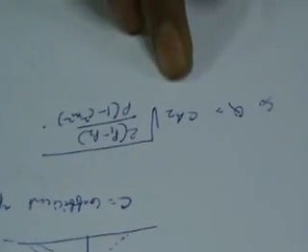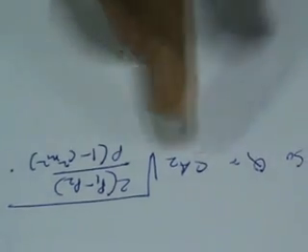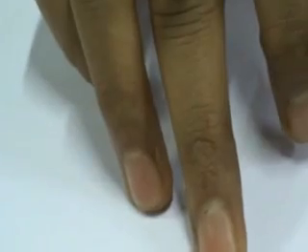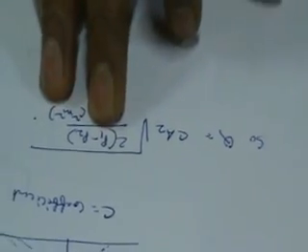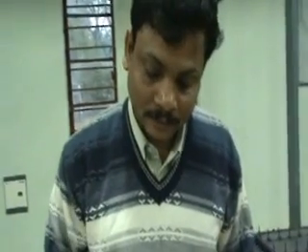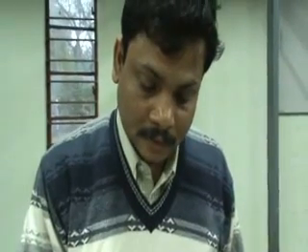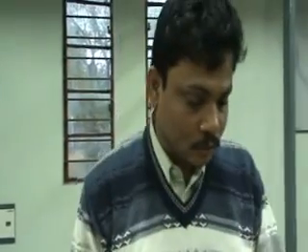Even though this is the actual quantity we should get if I know C, m and all those things, the quantity that is flowed through this will be somewhat less, because whatever the pressure across the orifice, P1, P2, there will be some other factor due to shock losses, because extra shock losses will occur. So the total pressure drops.